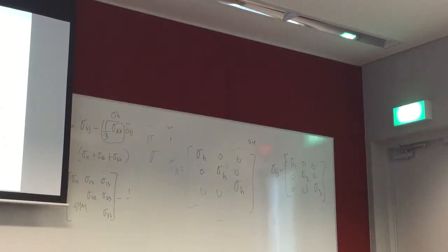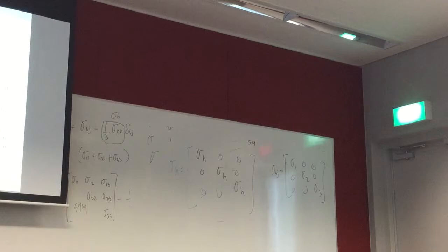In this case, you have high sigma 2, sigma 3, a multi-axial stress that is large enough. So you have high stresses in the 1, 2, 3 directions, and you're trying to achieve a so-called hydrostatic stress state. So to be able to yield, you have to have a very, very high sigma 1.